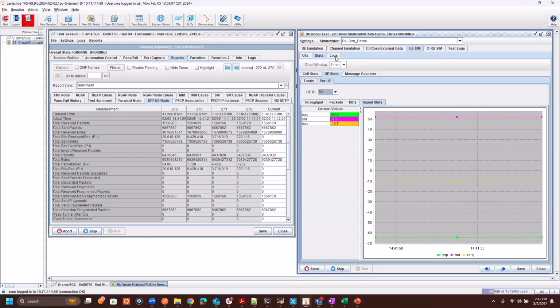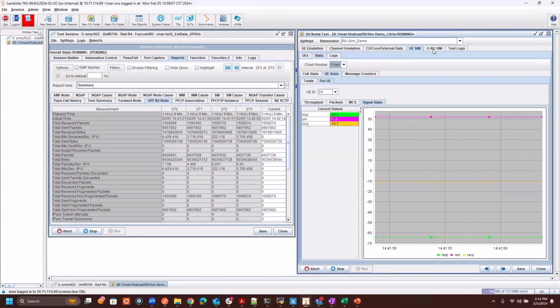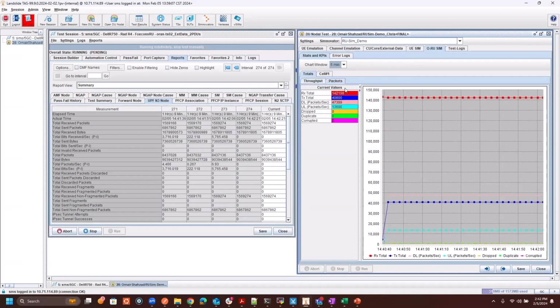The test solution provides details of log data to help DU troubleshooting besides performance testing. The log data includes quite a number of parameters, for example, error messages, packet loss, transmit signal power, and receive signal level, etc. All parameter logs are timestamped.